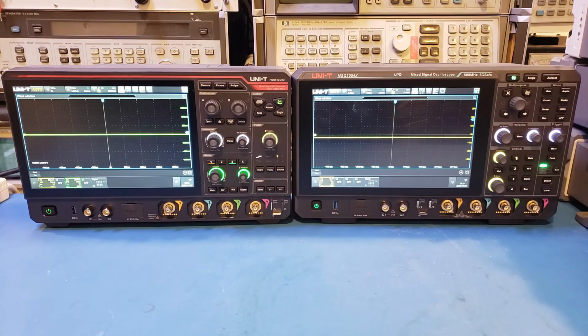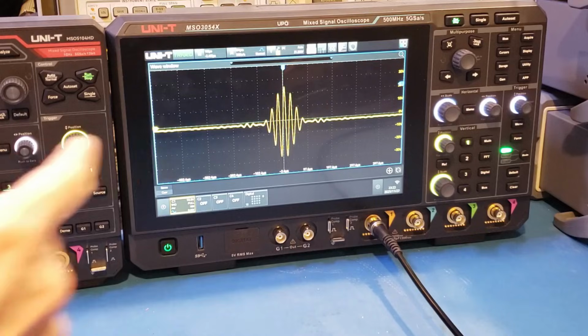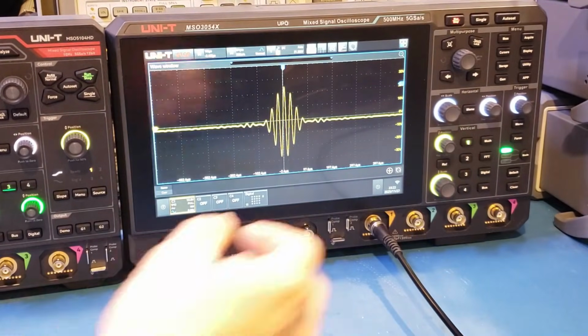That is actually important when captured signal has high dynamic range. And this is especially useful for doing analysis on rare signals captured via single shot. So let me demonstrate that. So for this demonstration, I'm actually capturing signal on the 3054X. This is a wavelet signal, and you can see here we captured the stable signal. Anyway, so now let me pause the acquisition. And now let's actually adjust the vertical scale.